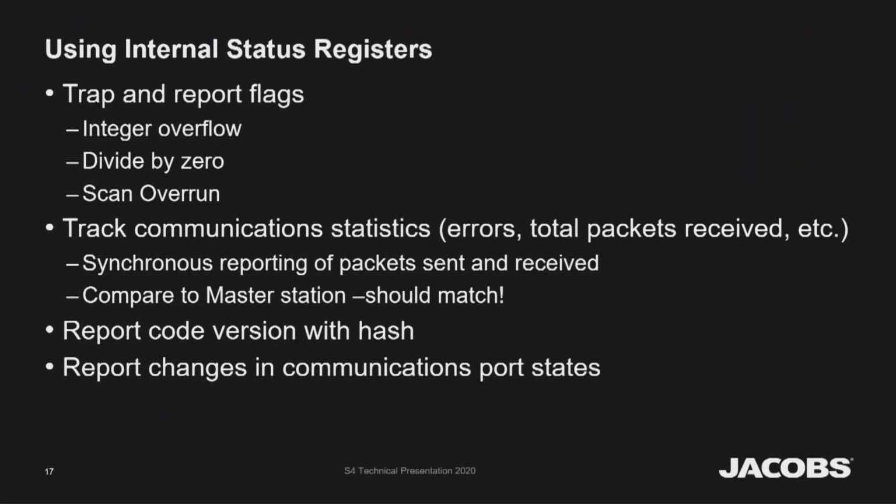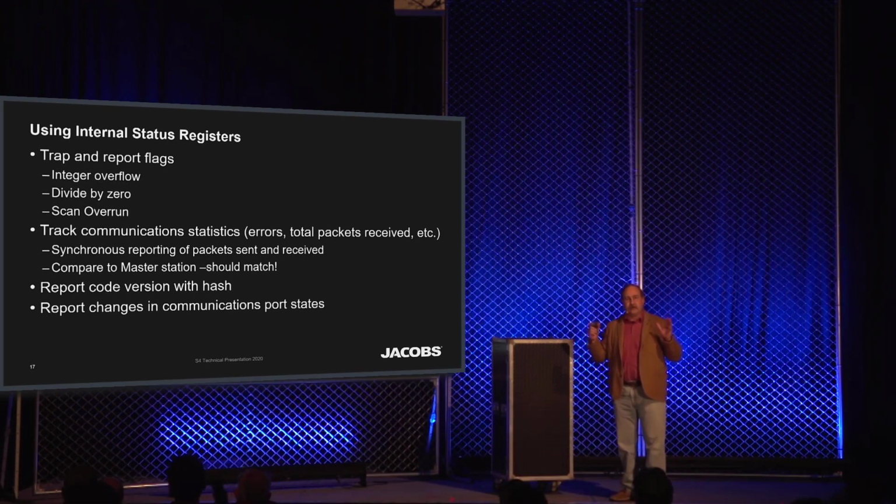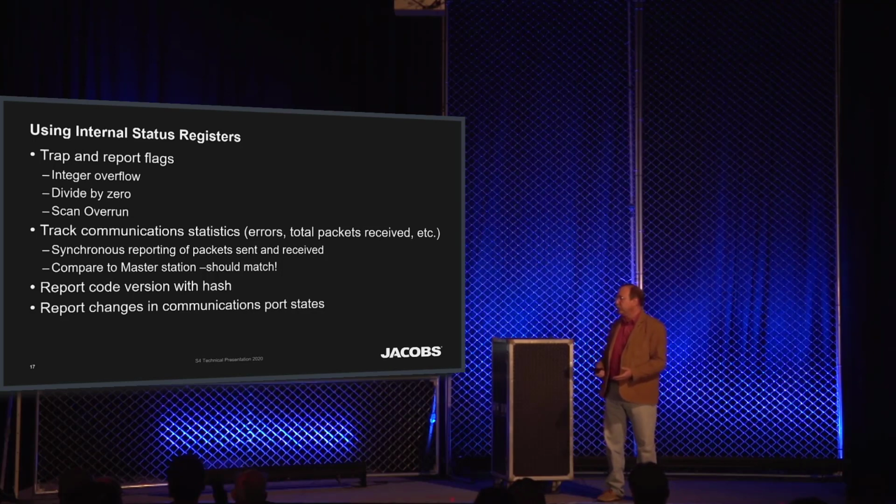There's also internal status registers. This is another thing. Ladies and gentlemen, just about all the PLC vendors have gone through a lot of effort to build diagnostics into the PLC. How many messages were received over a period? How many were sent? What's your cycle time? Have you done a divide by 0? What other kinds of things are going on? There's a whole bunch of diagnostics built into the PLC. Most people ignore them. I'm telling you, you should really check those things.